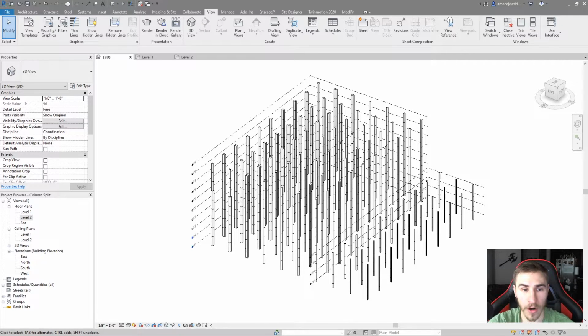So the 3D extents are those levels and grids and the extents that they cover in your model to create your 3D model. Now, the 3D extents that refer to levels and grids don't have anything to do with your model in that you can model everything normally. You can have everything modeled as you want it with the 3D extents not actually covering the model. And you'll start to see why you don't want that to be the case. A case like that would be if you have a giant floor plan and you have grids that cover like a quarter of it but not the rest of it. It wouldn't make any sense.